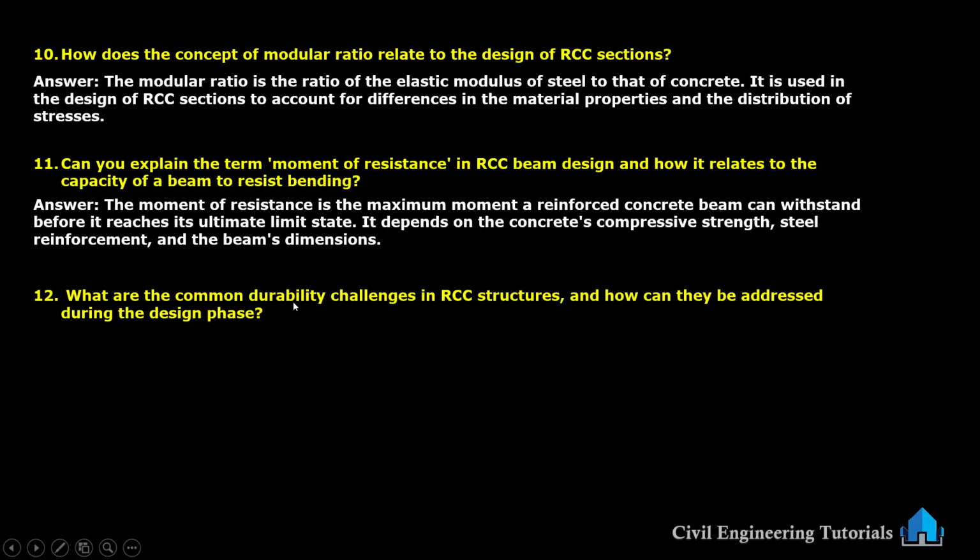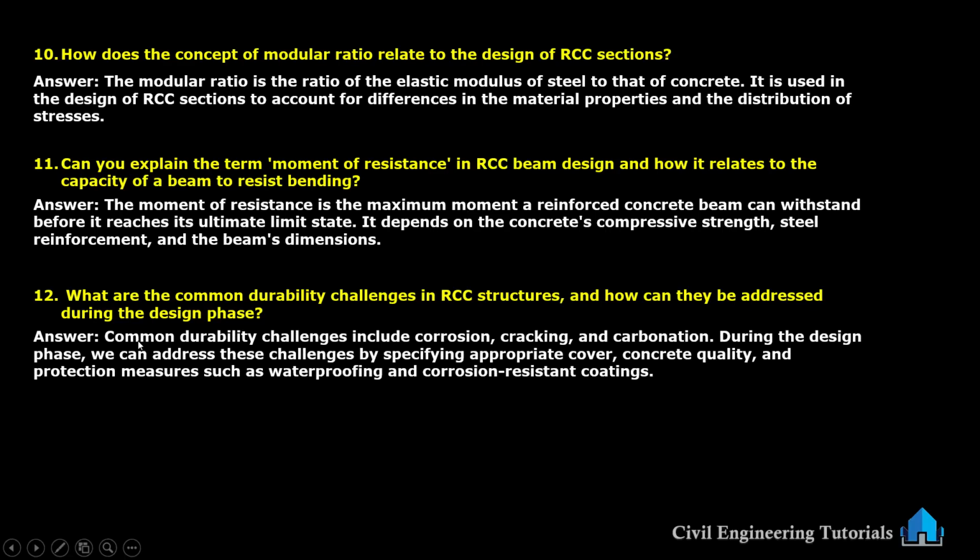What are the common durability challenges in RCC structures and how can they be addressed during the design phase? Common durability challenges include corrosion, cracking and carbonation. During the design phase, we can address these challenges by specifying appropriate cover, concrete quality and protection measures such as waterproofing and corrosion resistant coatings.